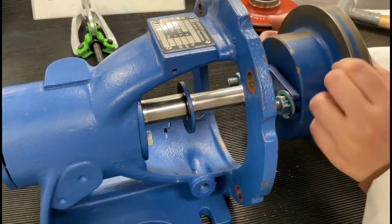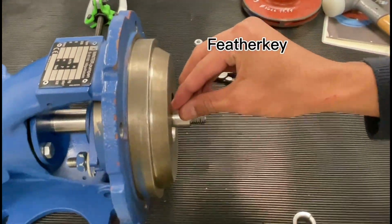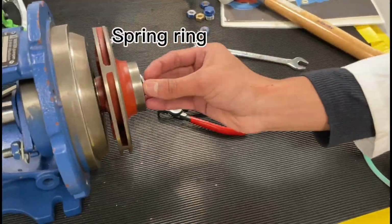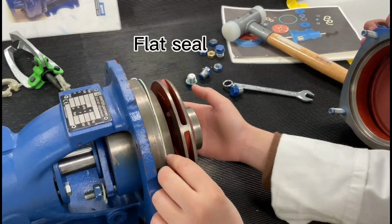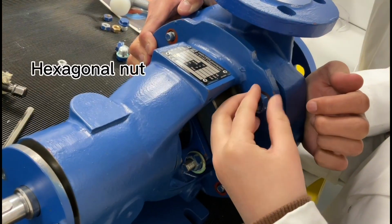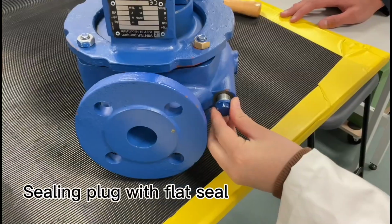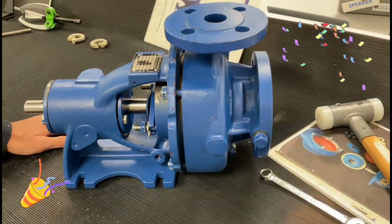Put them together and put the washer or ring and further key on. Add the impeller with spring ring and screw it with cap spring. Then put the flat seal before spiral housing and screw it with 4 nuts. Lastly, screw the sealing plug with flat seal in all 3 directions. Then we are finished with the centrifugal pump.